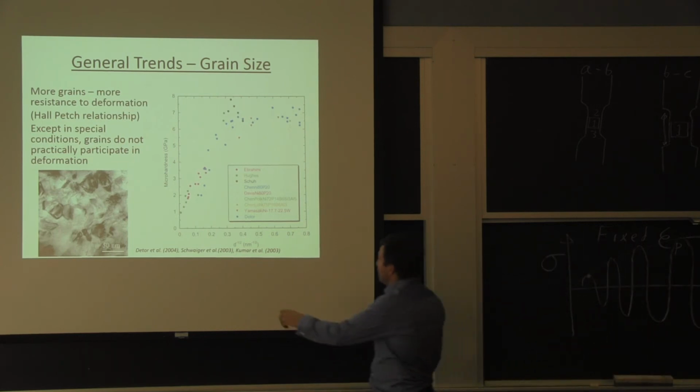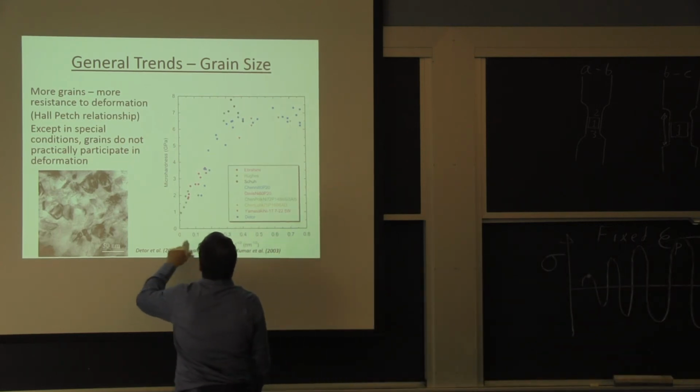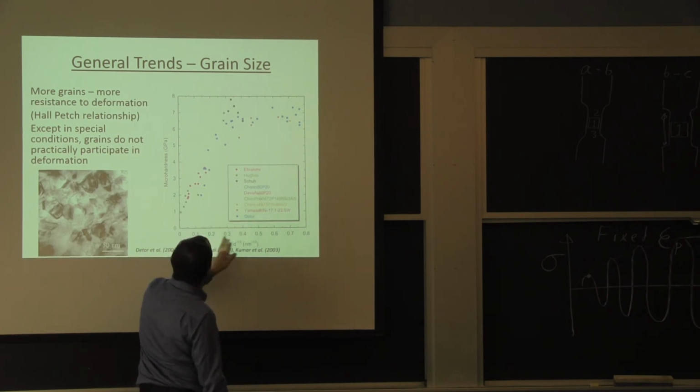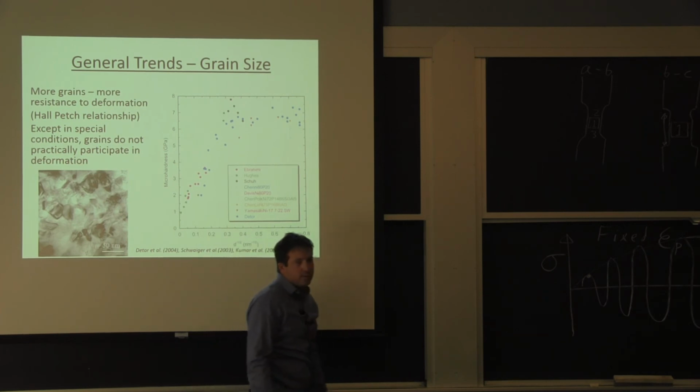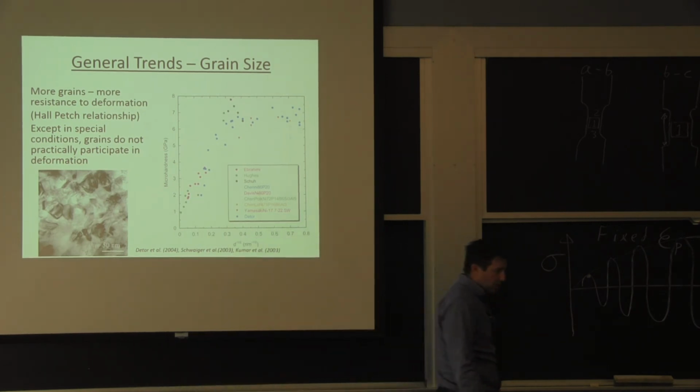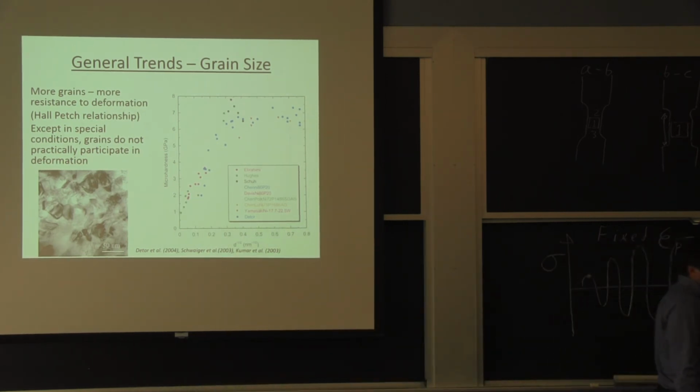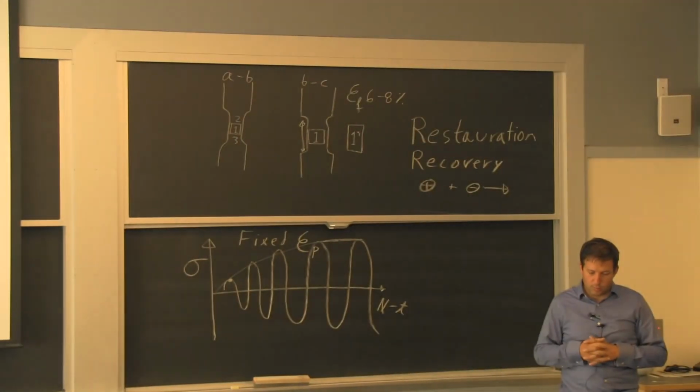And on this plot here of grain size against the micro hardness, when you're decreasing the grain size, you are increasing the strength significantly. It's a known fact, and that's the reason why we like to work the metal, the steel, quite a bit before we use it, so it has a fine microstructure. It's increasing the strength, and it's also beneficial for a lot of fracture properties.